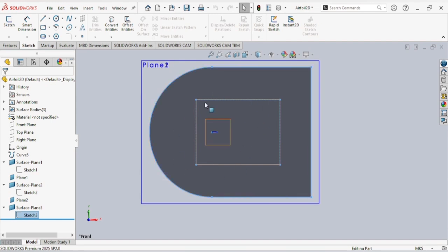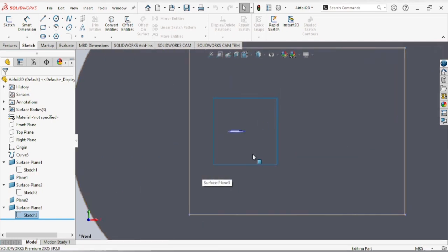To have better control over the mesh, we've created several nested domains around the airfoil. And an important note: when creating this nested surface in SolidWorks, the outlet boundary of each domain becomes the inner boundary of the next one in the following sketch.